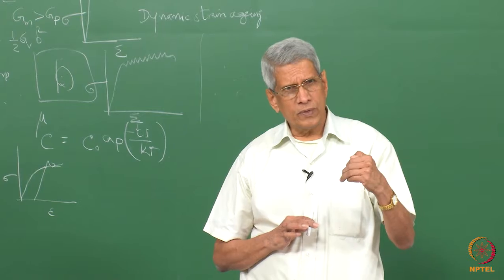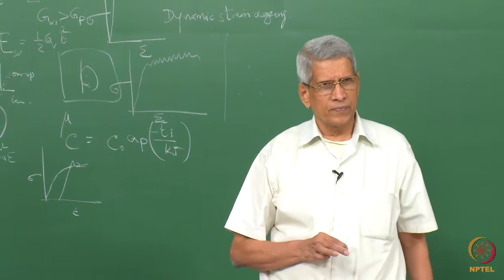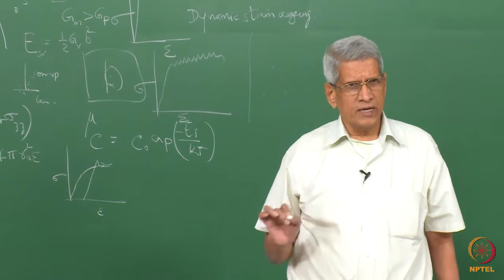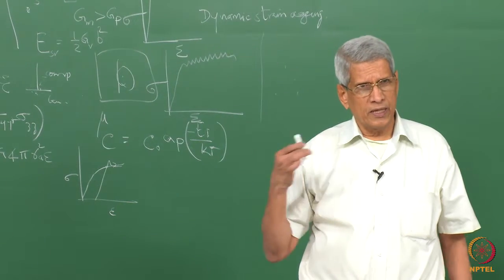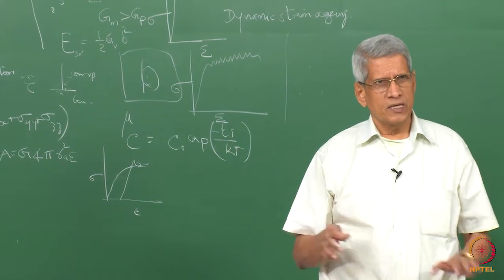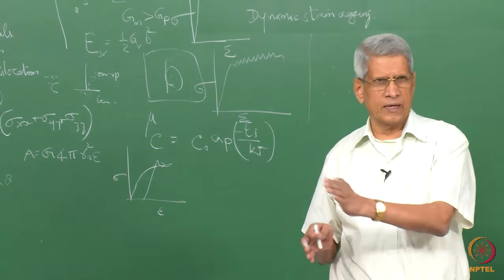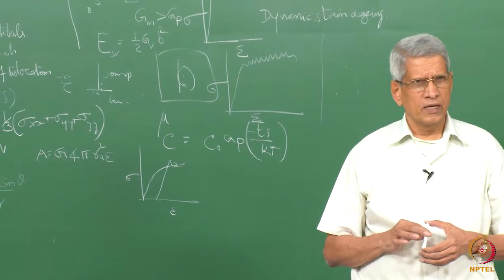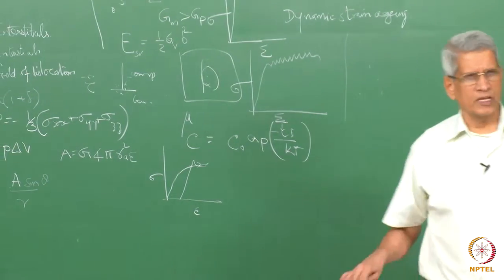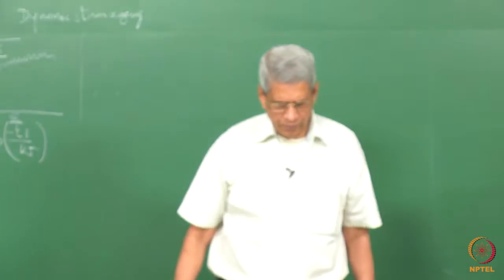We can say it in another way: the interaction energy which we considered, if we take its rate of change, will give a force. Some internal stress is being generated. Initially, the dislocation is able to move at a lower stress. Now we find that a higher stress is needed. Some internal stress which opposes the motion is created because of the introduction of these impurities into the material.